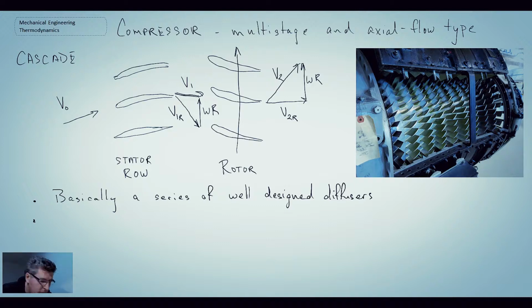And that's what a diffuser does, gives you a pressure rise. So it's providing a large static pressure rise without large total pressure losses.